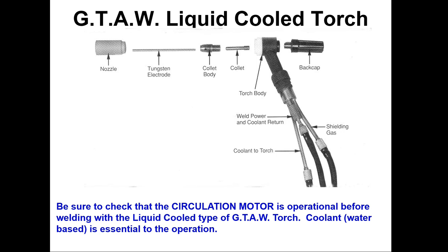So you got to make sure that the tungsten itself stays intact, and you got to watch that the tungsten's never loose. If you're TIG welding and you look down at your tungsten in the TIG, and it's jiggling on the end of the electrode, your tungsten is too small for the current you're running, and it needs to get bigger because it should be able to overcome. It's being overcome by all the heat. Tungsten, like aluminum oxide, melts in the 7,000 to 8,000 degree range. We'll talk about this in metallurgy, but when it gets to those stages, you got to make sure it's big enough so it won't drop away.